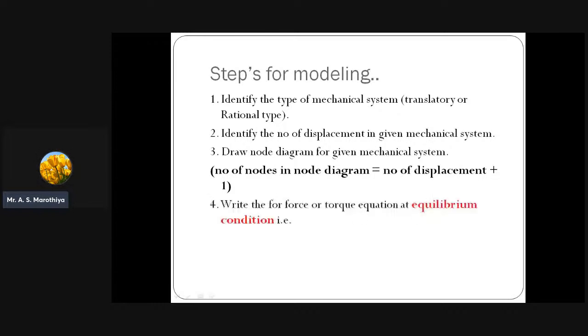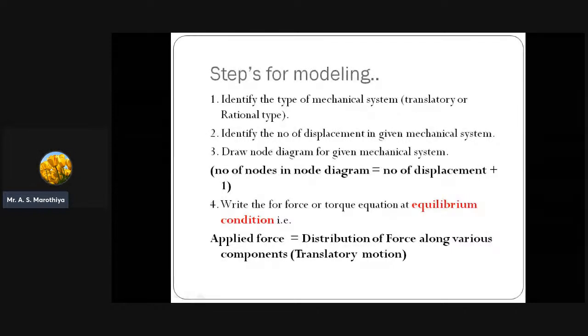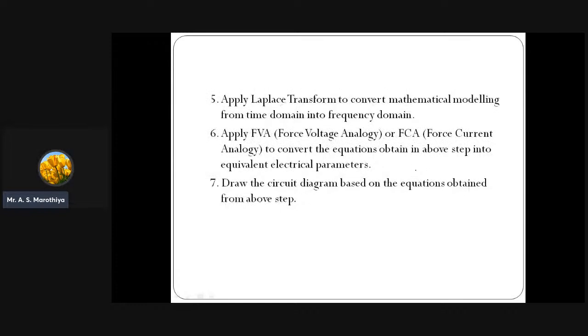Then we need to apply the condition at equilibrium, and finally we need to write the equations of force or torque corresponding to the type of mechanical system available with us. For example, if we are dealing with translatory motion type mechanical system, we need to write the equation of force at equilibrium condition. In the same way, if we are dealing with rotational motion type mechanical system, we need to write the equation of torque at equilibrium condition. And then we need to apply the Laplace transform to convert that into the frequency domain.